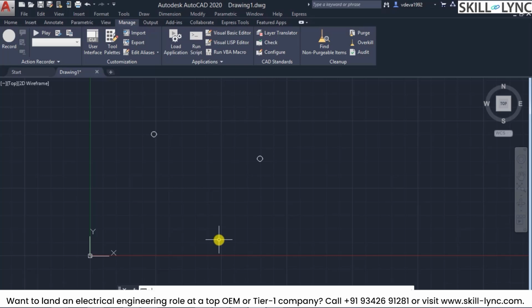The first is the load methodology, where we call it by the load command followed by the path of the command. We have to explicitly type the path. And the second one is using an AppLoad functionality, wherein you get a dialog box kind of environment where you can locate the file that is of interest to us. So let us first start off with the basic command.